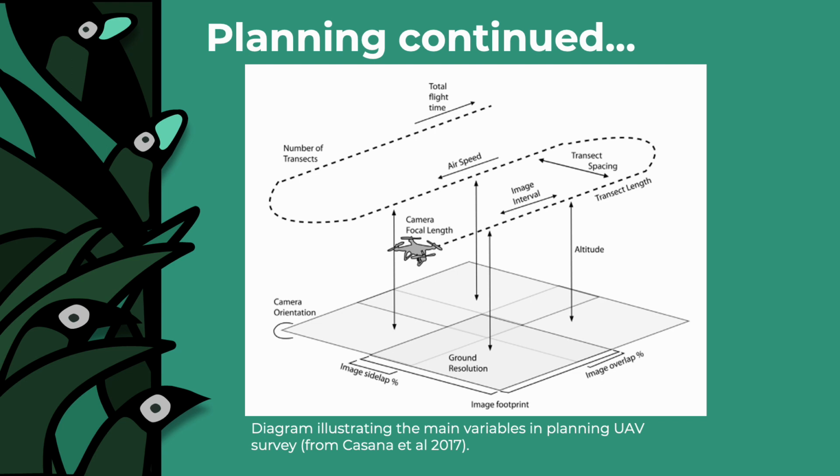Using an internet connection, maps, often Google Earth, provide geographic context to identify the flight area. After assigning the flight elevation, degree of image overlap, and flight speed, the planning software automatically establishes flight transect lines. The completed plan is saved for upload to the UAV at flight initiation, whereupon it will automatically take off, complete the flight transects, and return to the landing zone. However, the pilot can regain manual air control at any time.